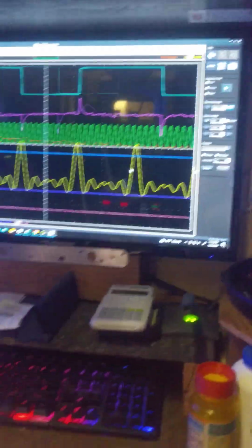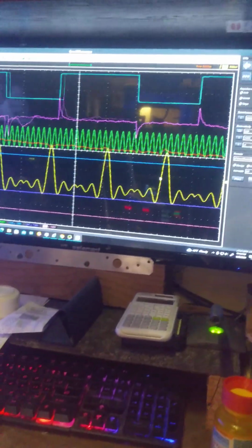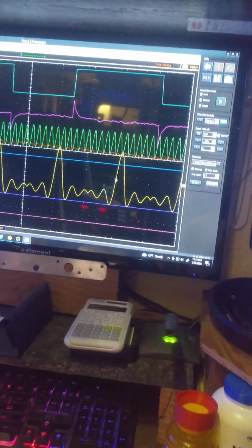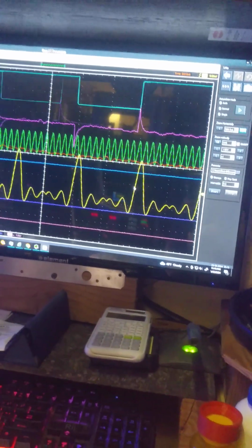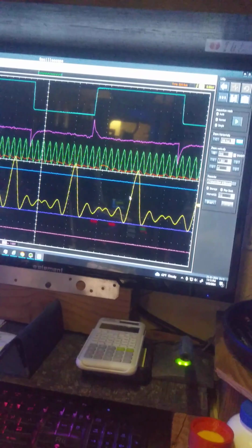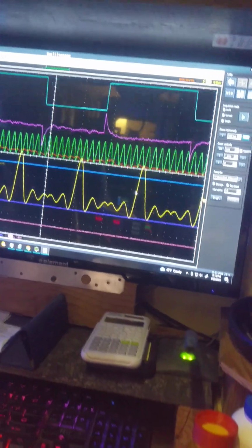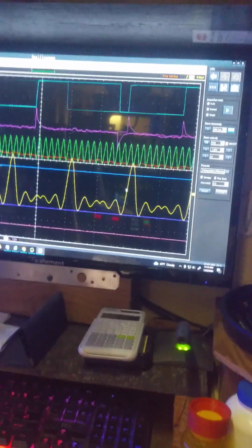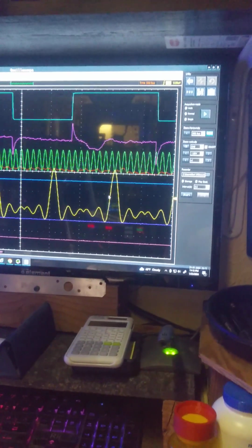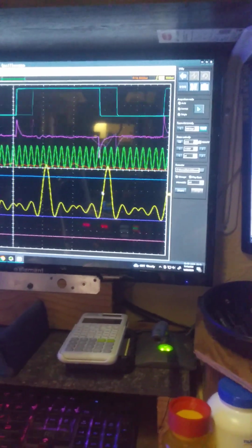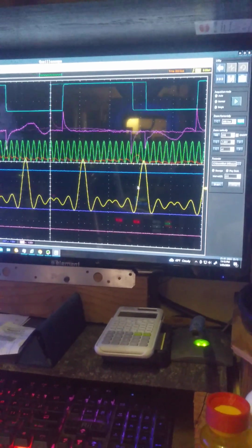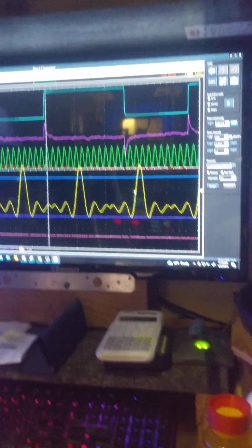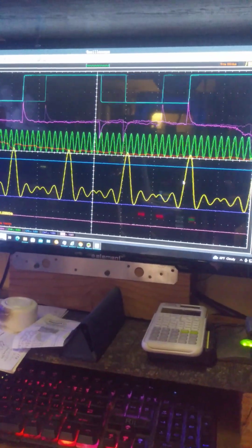That's an Arduino-based version of this. But again, its sampling rate's going to be maxed out. I can't remember, it's been a few years, but like 40 kilohertz or something, and its usable signal I think was like 5 or 10 kilohertz. But again, it Nyquists out just like this does, so I was rather disappointed to see that. At any rate, this basically shows you the pitfalls of Nyquist and this piece of equipment too. So, anyway.